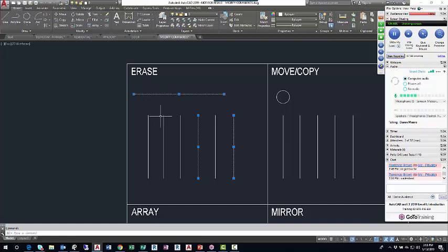These are all left clicks. There. All those objects stayed selected. I didn't hold down my shift key or my control key. AutoCAD has this auto-accumulate behavior where if you select one thing, that thing stays selected even if you select other things. And that's by design. In AutoCAD, the assumption is you're going to select multiple things all the time.